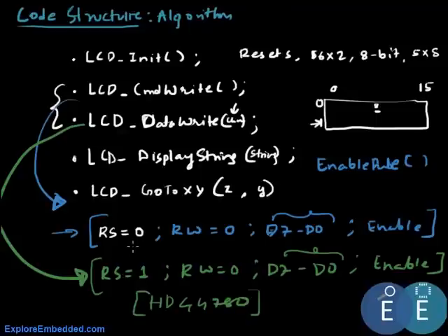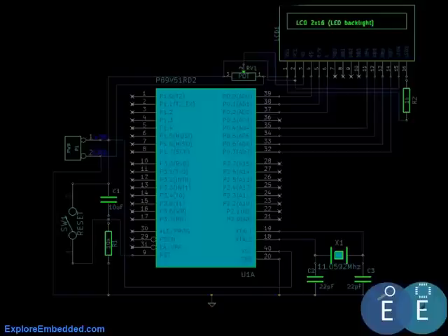So these are the basic commands and how the LCD uses them. Now the only difference for the 4-bit mode is the commands that we set to initialize the LCD. As we will discuss, the function set, instead of setting it as 8-bit, would be for 4-bit. We'll go through the code at the end. Before we do that, we'll see what the difference would be for the 4-bit mode.